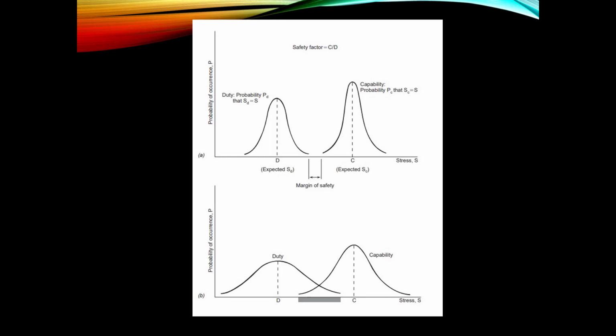So for example, on the bottom figure, you see those two curves overlap, and there's an interval there where you're at risk of having a bridge built that can't handle the load, which could lead to a catastrophic failure. So the safety factor used all by itself only works if it is so big that you can't have any overlap in those two parts of those curves.